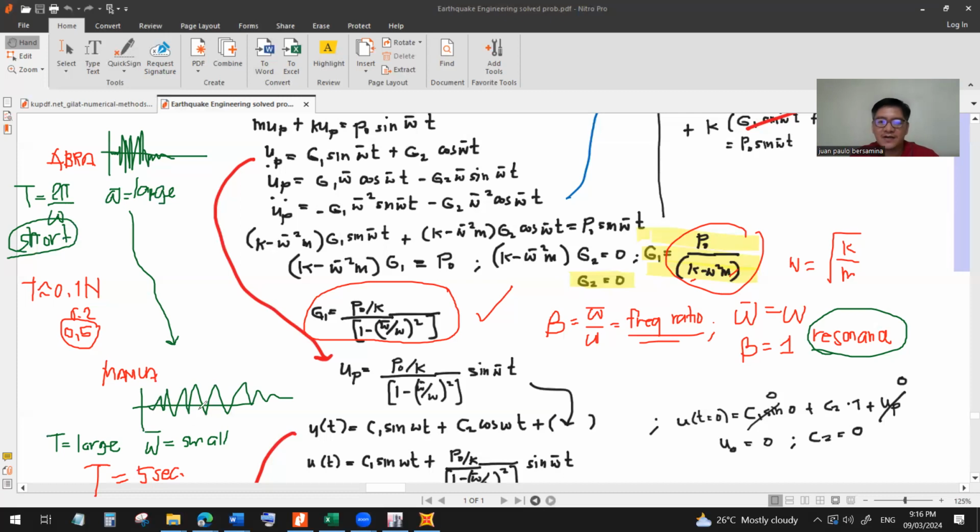Okay? So for high-rise buildings, there's a possibility of resonance, but it doesn't mean there will be damage. So short period structures near the epicenter are worse off because the wave will resonate with them. So, that's one of the applications of this concept.